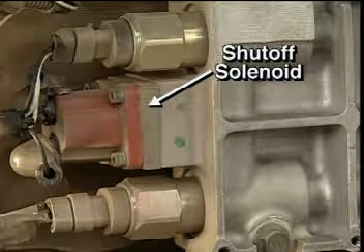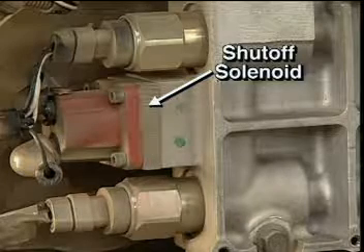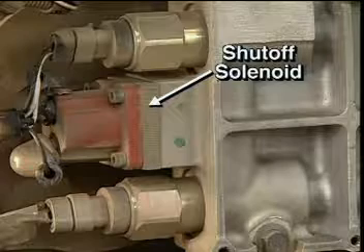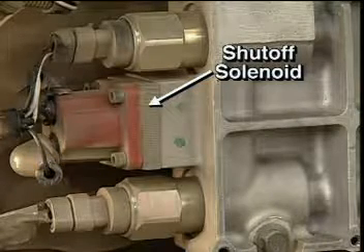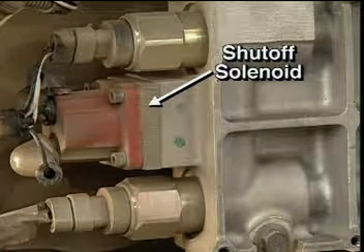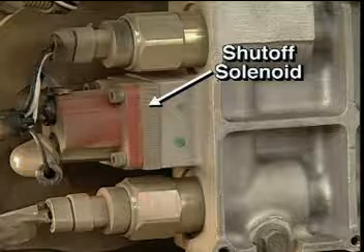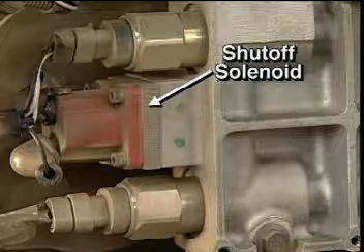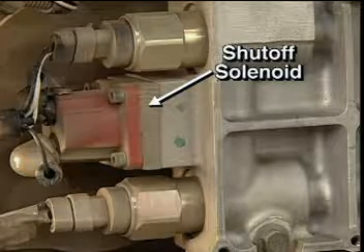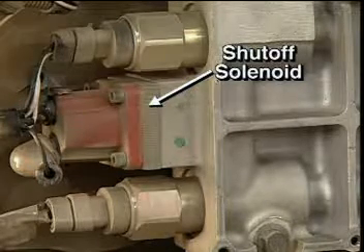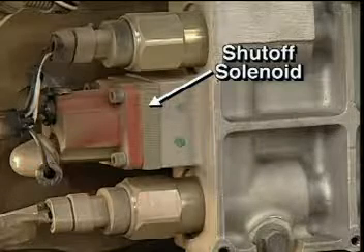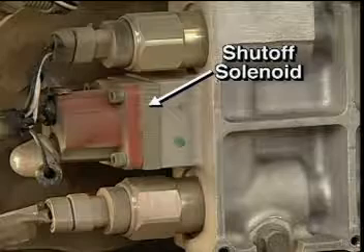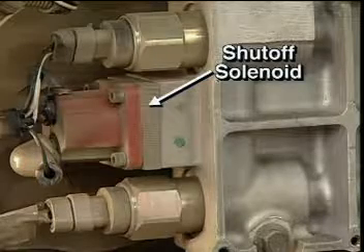The fuel shutoff valve engagement delay feature slows the opening of the fuel shutoff valve during warm engine starts. The coolant temperature is used to determine when this feature delays the opening of the shutoff valve. With a warm engine, the fuel shutoff valve is not opened until the engine speed is above the threshold for a calibrated amount of time. This allows the fuel pressures in the timing and rail passages to become stabilized for improved fueling control, which reduces engine noise during hot engine starts.